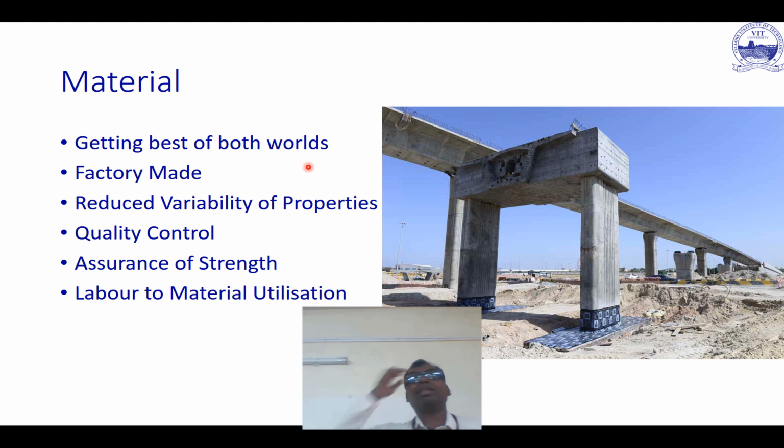See, one of the things that happens: what happens to the Young's modulus of steel when you are increasing the ultimate tensile strength? The bars which are used in the tendons are not the same steel bars. What is the Young's modulus of the ordinary rebar, and what is the Young's modulus of the other one, what you're using as tendon? It is the same. Okay, but now I am increasing the cube strength of concrete. What happens to the Young's modulus of concrete? It increases. It keeps on increasing.